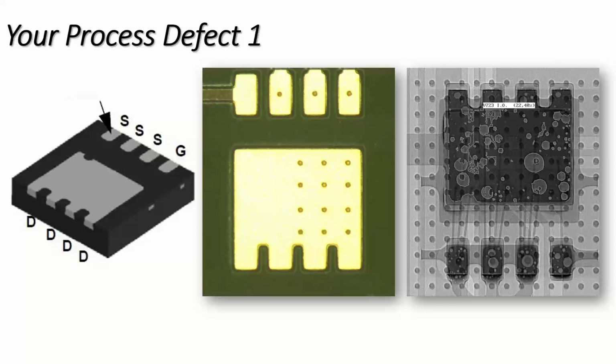So that's one thing that can be done. But fundamentally, if the board is going to outgas, or anywhere around the board is going to outgas, that can particularly give you this problem. There is a limit to what you can do with any solder paste technology and profiling. And if you've experimented with, as I understand the customer has, different profiles, different pastes, etc., then it's not the norm that is causing the problem. So by improving profiling and paste, yes, you can improve void formation, but we're trying to get to the nitty-gritty.